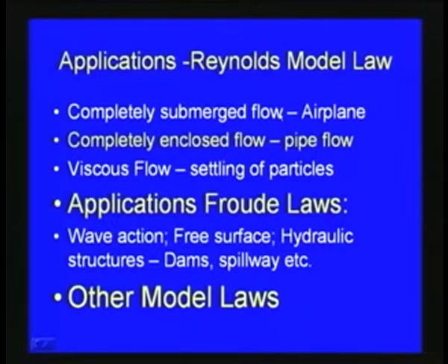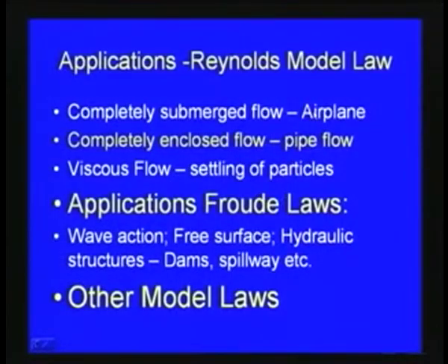If you are modeling, say, an airplane in the laboratory, we generally consider the Reynolds model law, and for a completely submerged airplane or torpedo, all these kinds of modeling we will use the Reynolds model law.